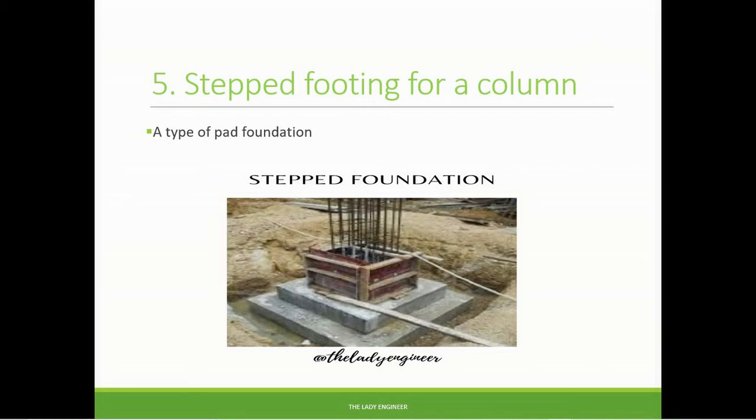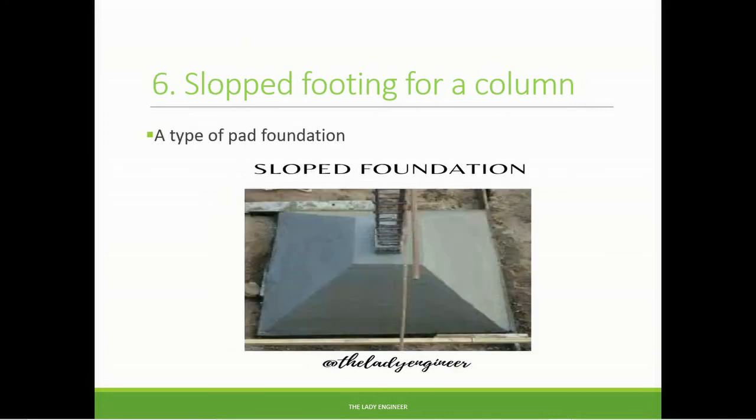So you can actually step even the strip foundation, and I'm sure most of you have seen this type of foundation where you use the strip footing type of foundation which I mentioned earlier, but you step it because the natural ground has a slope. Then you also have the sloped footing for a column, which is also a type of pad foundation as already mentioned earlier.